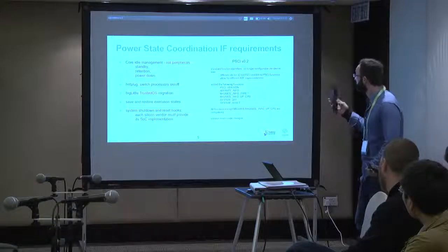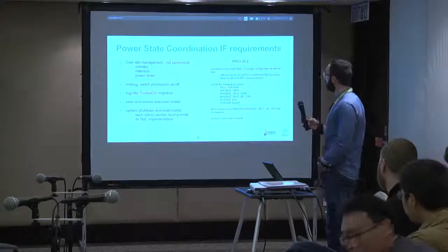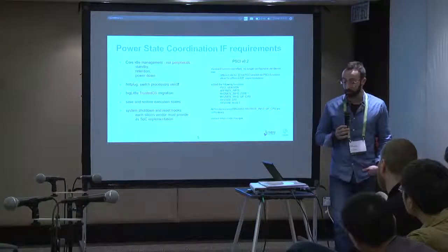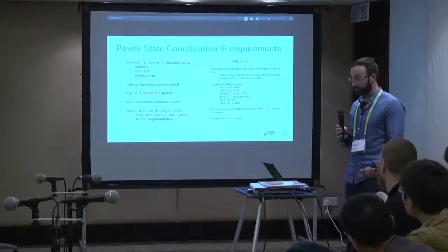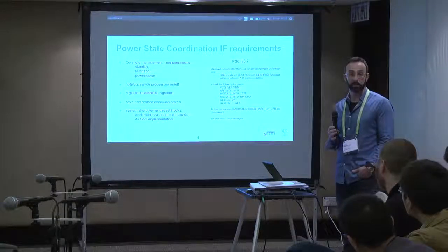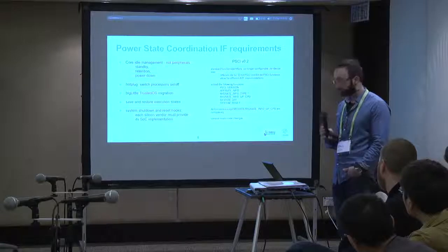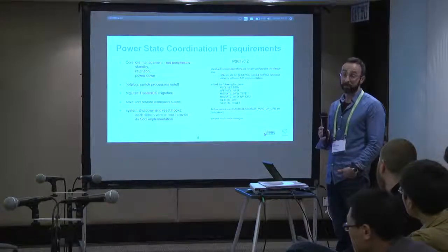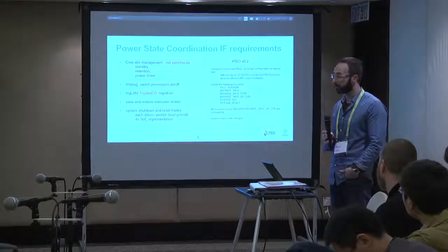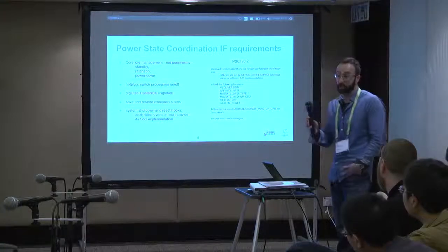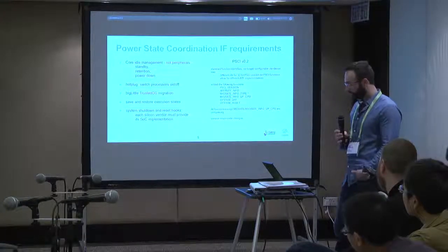Then, of course, since we have power down there, save and restore execution states needs to be present. All the GIC states need to be saved. So that will be part of the firmware. The untrusted firmware or the platform specific areas of the firmware will take care of the GIC, as well as the caches and so on.